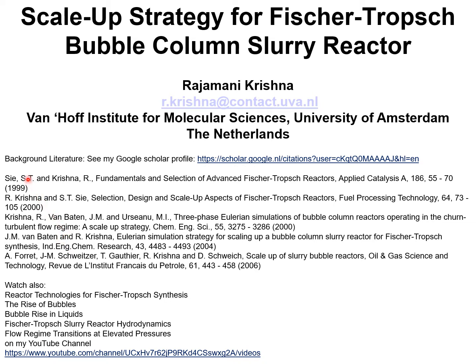The papers with C describe the technology for Fischer Tropsch synthesis and the choice of the bubble column slurry reactor versus the alternative multitubular trickle bed reactor for the same process.